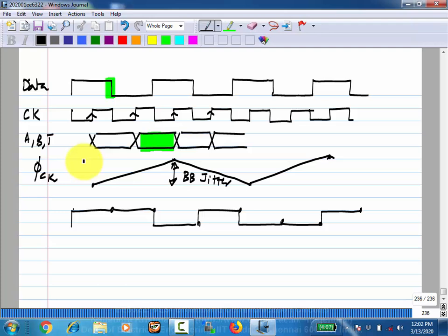Remember again, the system we were considering was one where the VCO was at the exact frequency, and you are only providing phase correction through the loop. Okay. This is analogous to assuming a very large capacitor, so that in each cycle the change in the capacitor voltage is not much. So then what do you think happens? How much will be the bang bang jitter?